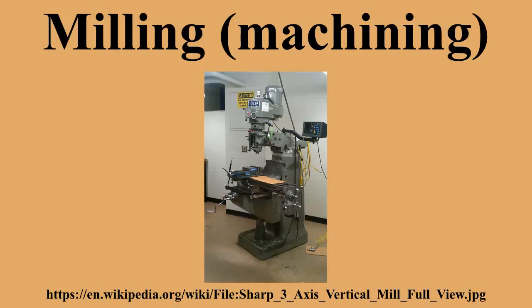hypoid gears. Comparative merits. The choice between vertical and horizontal spindle orientation in milling machine design usually hinges on the shape and size of a workpiece and the number of sides of the workpiece that require machining. Work in which the spindle's axial movement is normal to one plane, with an end mill as the cutter, lends itself to a vertical mill, where the operator can stand before the machine and have easy access to the cutting action by looking down upon it.